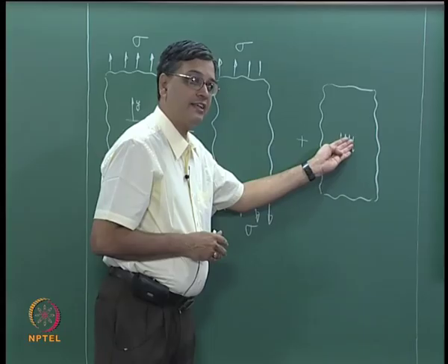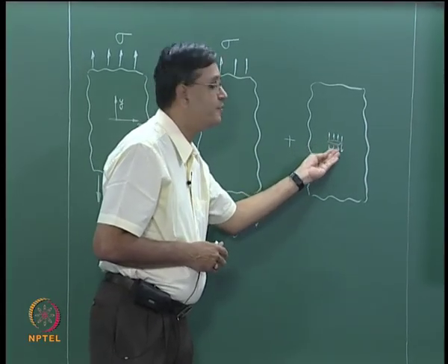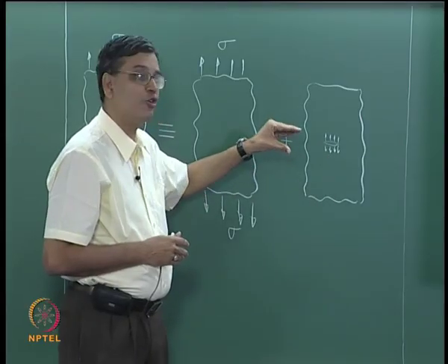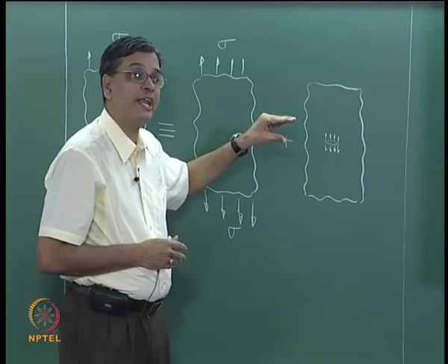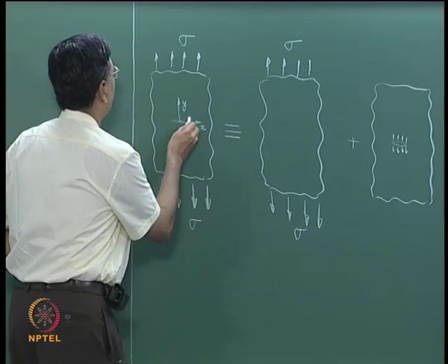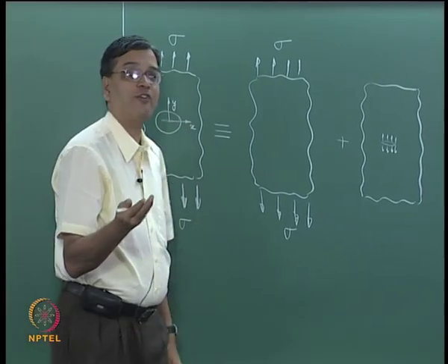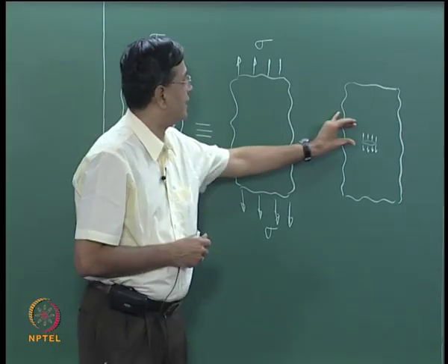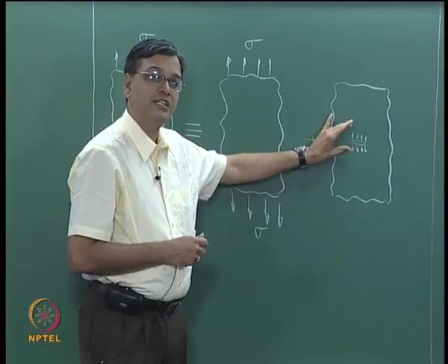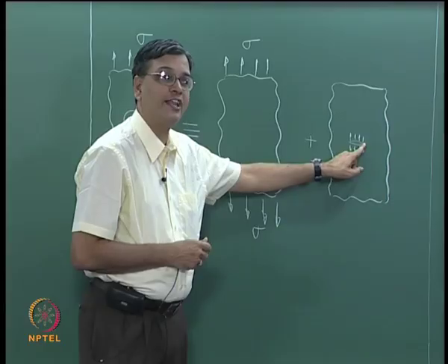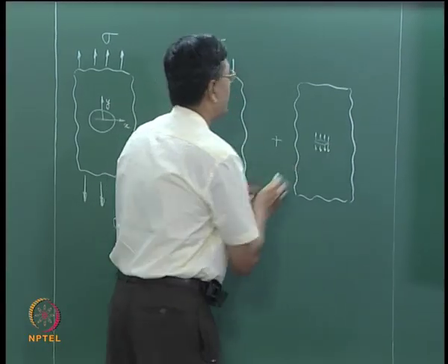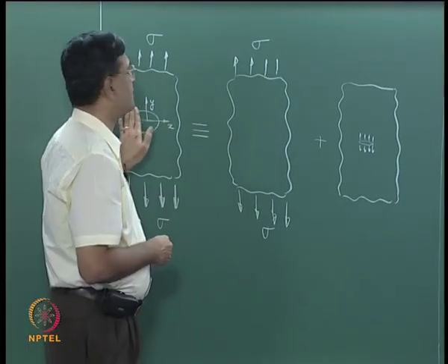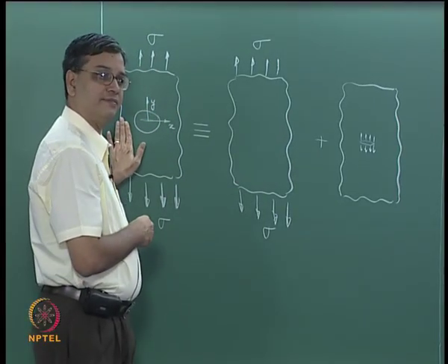Here I have a crack and I need to know what should be the load, that is also needed. The crack needs to get opened up and it should be opened up to the extent that what we have already got as your crack opening displacement. So, if I maintain the crack is opened up by a suitable force system, that would automatically specify what is the singularity in this crack tip, it will model the crack behavior, and when you add these two problems, this problem is possible.